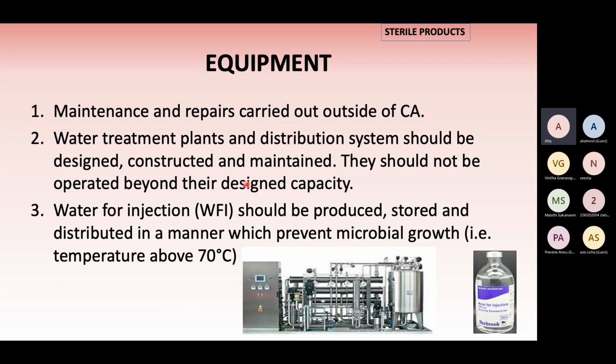Just make sure that they are not operated beyond their capacity. Water for injection should be produced, stored, and distributed in a manner which prevents microbial growth. The temperature advisable is above 70 degrees Celsius.